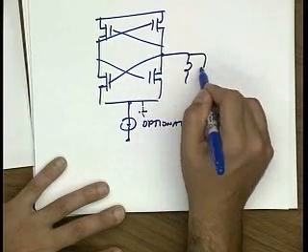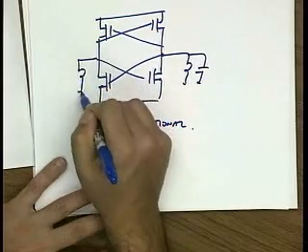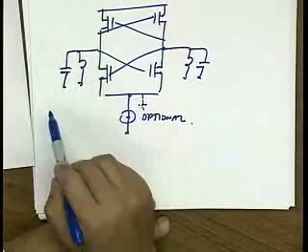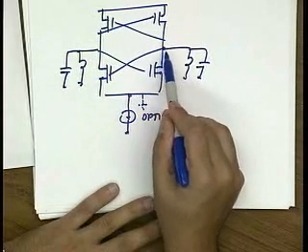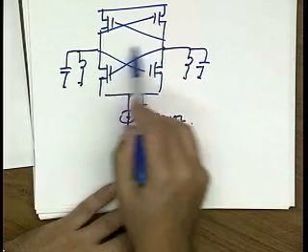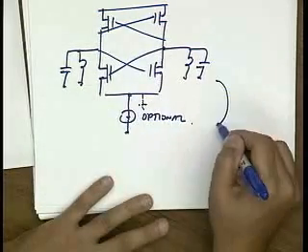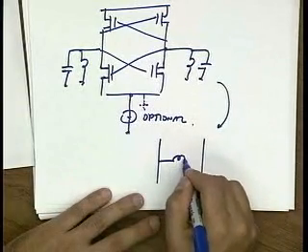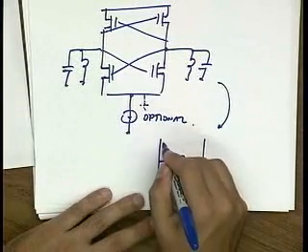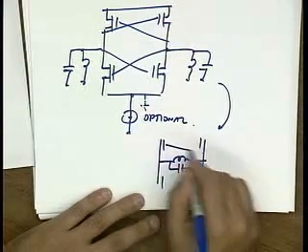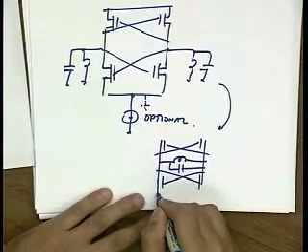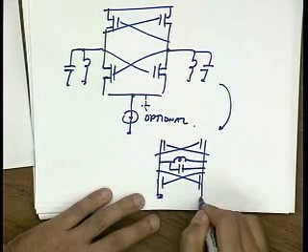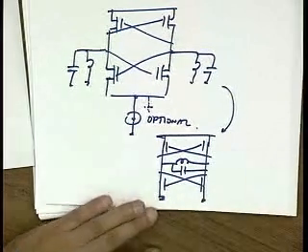And then, of course, you have the LC tanks here and here. And then, just like before, there's no reason to have two LC tanks to ground, especially because this ground node would interfere with the bias point here. It's much better just to connect the LC tank across. So finally, let me draw a quick version of this. I have my LC tank, I have my transistors cross-coupled, and let's say connected to ground. Okay.